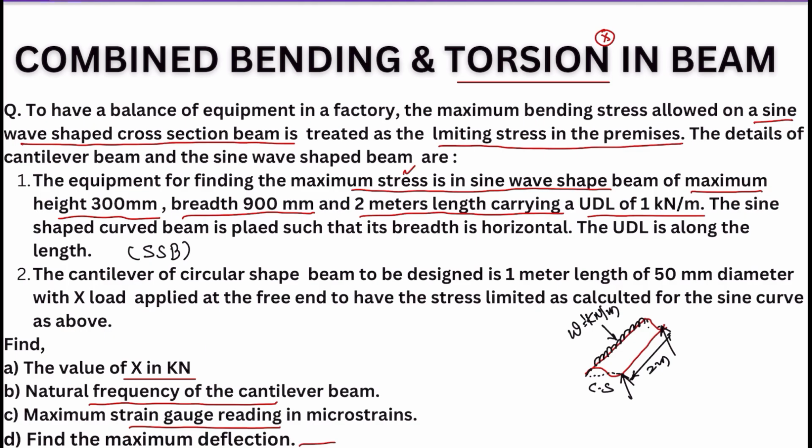Now, the cross section comes into play when we have to find out the bending stresses. Cross section will not have any bearing on the calculation of bending moment. Irrespective of the cross section, the loading and length of the beam decide the bending moment. Stresses will be calculated on the basis of I and Y. I and Y can be calculated from your cross sections.